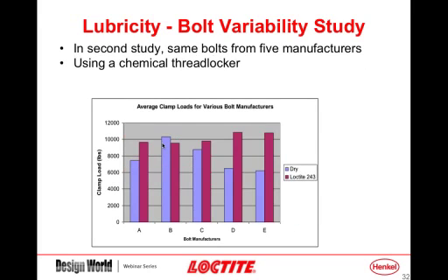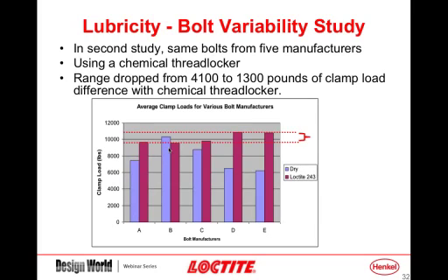So then in the next we repeat that exact same test, but in this case these were the dry results with no material applied to the fastener. These are the same bolts, well, same manufacturer's bolts. They were new bolts that were reassembled using a liquid thread locker on them. And the observation that we had is that we had much less scatter in the clamp load.